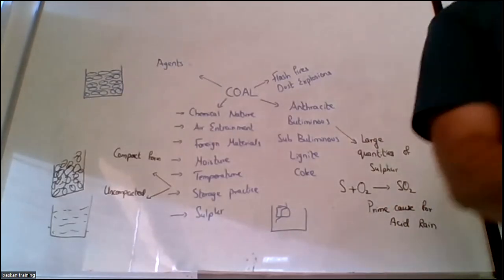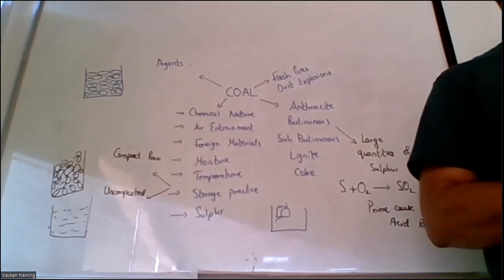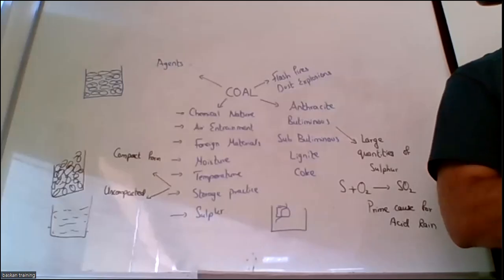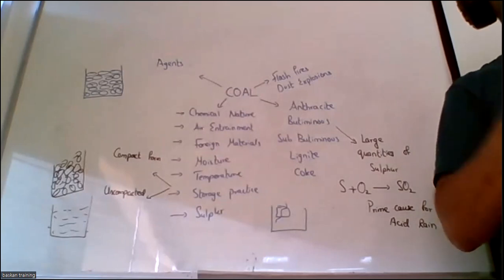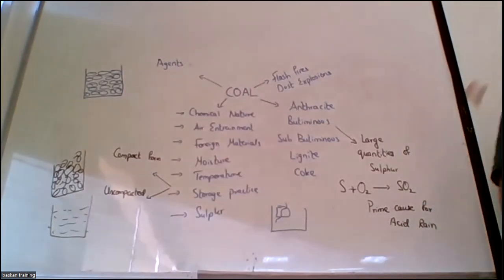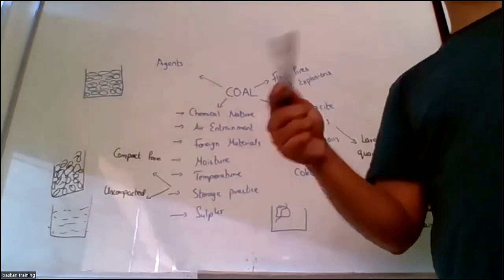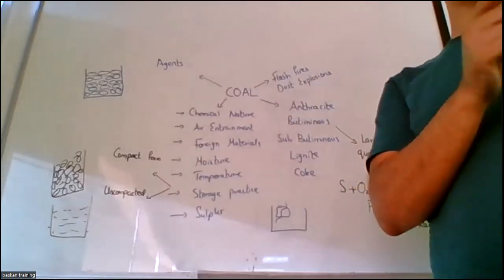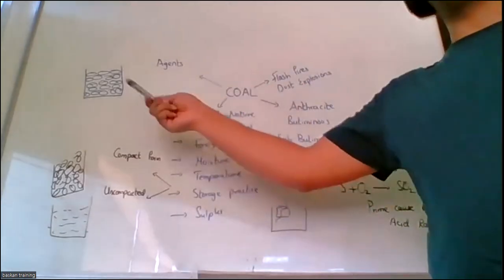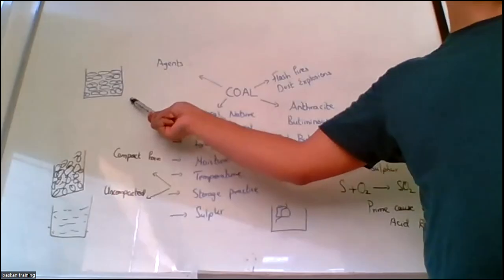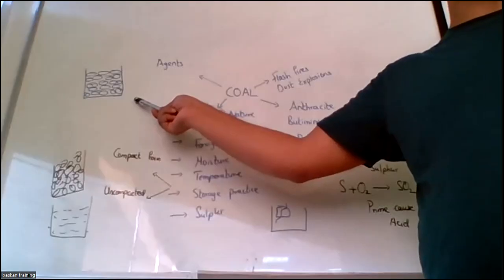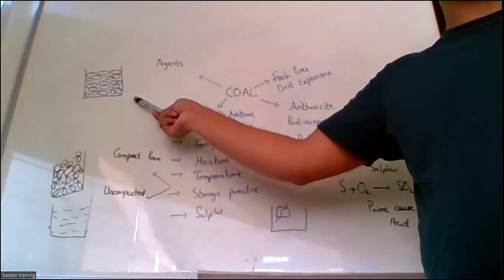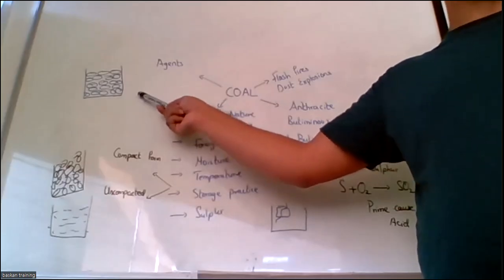Water we can apply, but water is not considered the right agent for coal fires. Water is a wrong agent. And why do we usually say water is a wrong agent? Because water converts to steam, and that is why I was saying the volume has to be kept in consideration. The tank has a volume, right? So when you apply water, steam is generated. Steam occupies a larger volume. Internal pressure of the tank is going to exceed, which will result in vapor cloud explosions. So that is why water is a wrong agent.